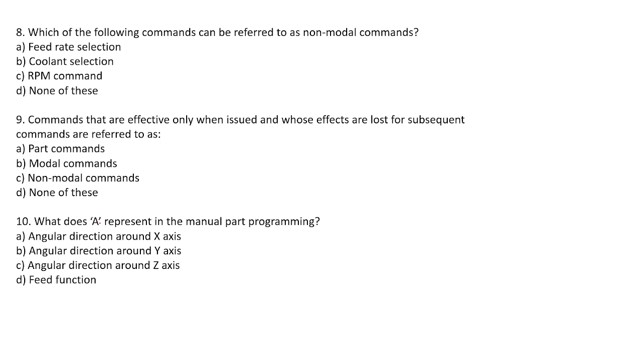Okay, now coming to modal and non-modal commands. In your machine tool or machine table, the origin is located at some position on the machine table, usually at the southwest corner or lower left-hand corner, but not necessarily.